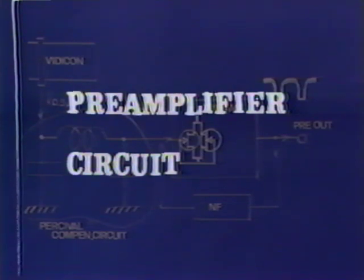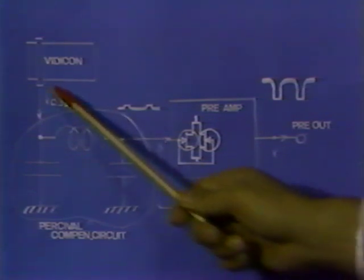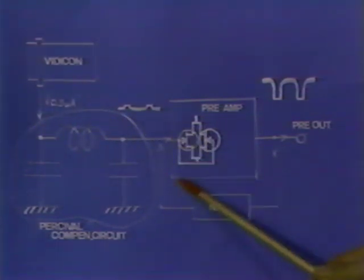Preamplifier. The preamplifier is the system to boost up the delicate signal from the camera tube to make the signal processing job in the following circuits easier. The most important thing about the preamplifier is the signal-to-noise ratio, because it amplifies the delicate signal from the Vidicon. So practically, this preamplifier's SN ratio is the determinant of that of the whole camera system. Therefore, many features to improve the SN ratio are found in this circuit.